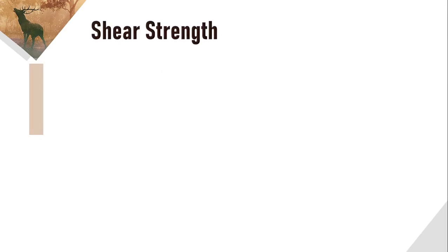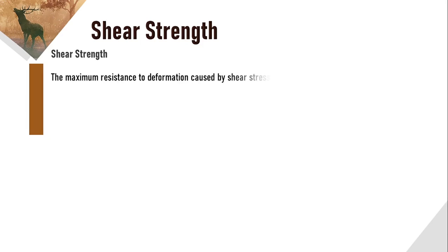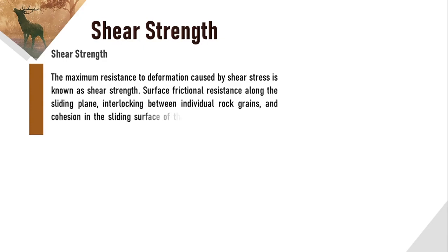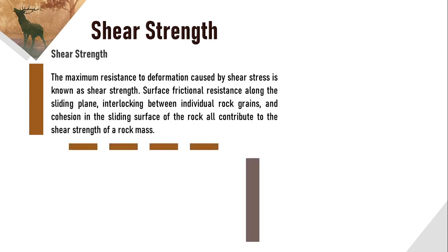Shear strength. Shear strength is the maximum resistance to deformation caused by shear stress. Surface frictional resistance along the sliding plane, interlocking between individual rock grains, and cohesion on the sliding surface of the rock all contribute to the shear strength of a rock mass.